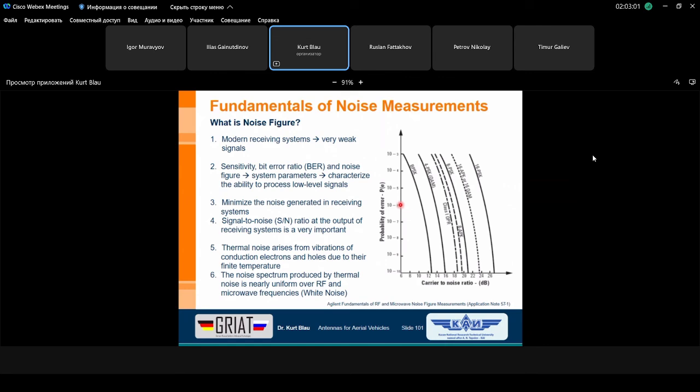And to hold this very good probability of error, as shown here, our signal to noise ratio must be better. That means the signal we receive, regarding the internal noise produced by our active elements and the thermal noise coming from the environment over the antenna, must be at minimum or better, for instance, 12 dB.